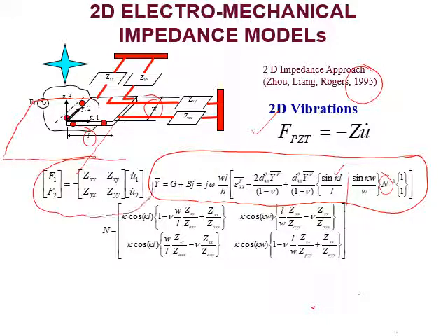We have the two forces in the x direction and the y direction, and then we have the direct impedance as well as the cross impedance. So if you expand this matrix, you will find that F1 depends on both U1 dot and U2 dot. So we have the direct impedance and the cross impedance. So total there are now 4 impedance terms.